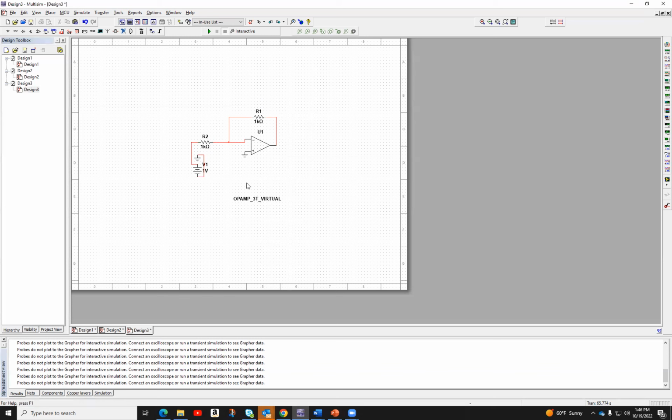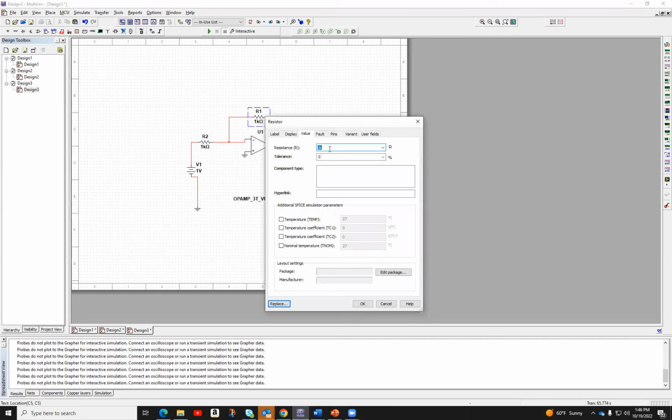and I want to see what happens when this runs, right? So according to the theory, what I will have is an inverting amplifier, which amplifies the signal. Well, in this case, it's not going to provide amplification because they're 2 1s. So 1 over 1 is going to give me 1. So let me make this one a 2. And let's see what happens. 2K.